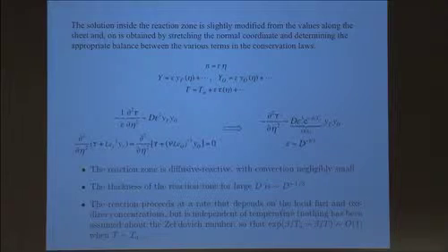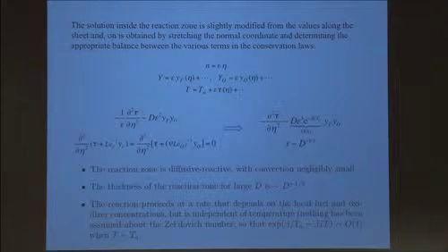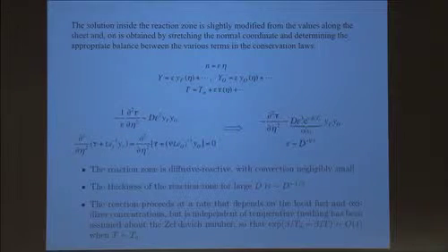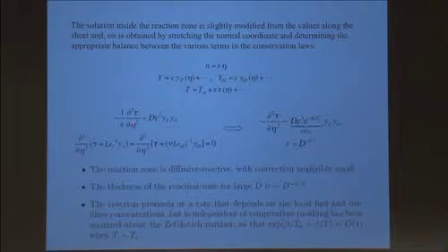And now if you substitute this in the equation, similar to what we have seen in premixed flames as well, usually in the thin reaction zone, the important thing is diffusion compared to convection. Convection is usually negligible compared to diffusion. And so the diffusion terms survive with the 1 over epsilon coming from the stretching.